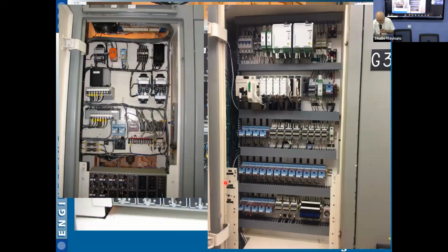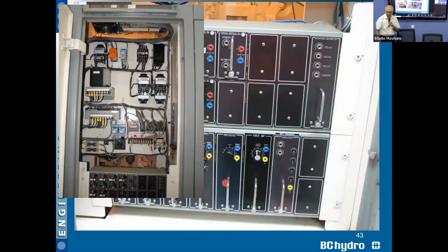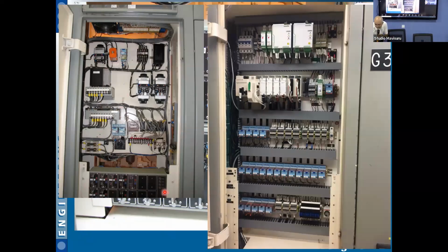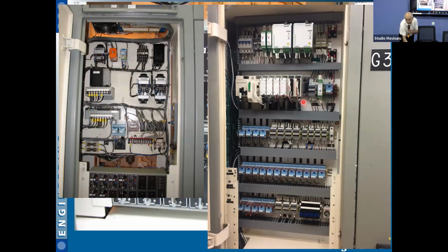I want to share this picture. I know that in our case, it's our practice to replace the full governor system if something goes wrong. This is one example where we replaced it partially. Here is an analog governor. You see that the black boxes are the electronic cards pushed into the card cage. This is the one that is expanded, the place where you have the electronic card. This is the expanded view of that electronic card, and you have some relays up here. What we did here is we manufactured a PLC based governor and ripped this panel out. We tested this before the installation, because you have this panel, you test it to make sure that everything works, and then we took a 1 day outage, put it over here, and commissioned the governor within a couple of days.